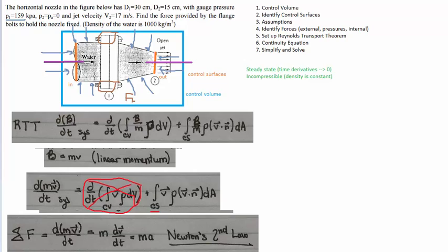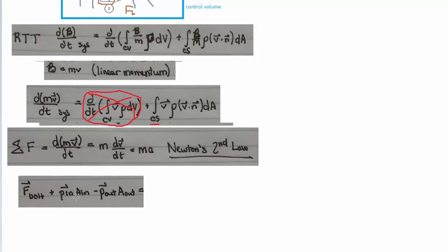The reason for that is what I was saying before. When you're working with pressures, that means you have air pressing in to the object or system you're looking at every spot. Now on the left, that means that the pressure is going rightward, which we defined as positive, and on the outlet side, the pressure is facing inward, so that means it's going left, which is negative. That's why you see over here this term is positive and this term is negative.